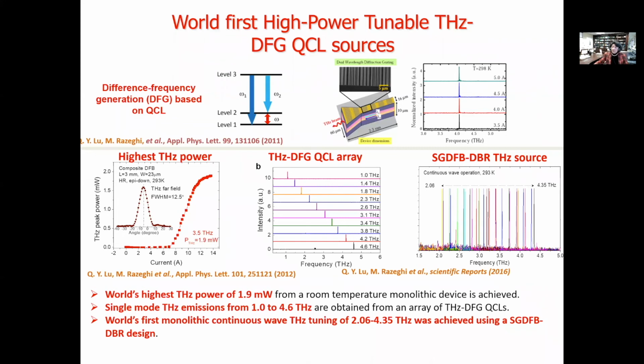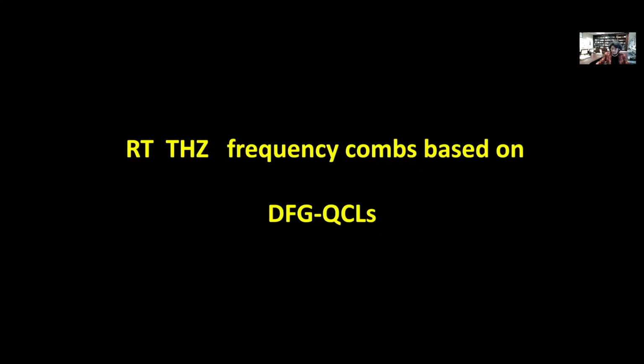And I have to say that one of the most important parts, if we look at the emitting spectra at 4 terahertz as a function of temperature and injection current, is that we have no change of the emitting spectra. That is for telecommunication. For many applications it is excellent because it is based on the DFG. Not the same way for the frequency comb.